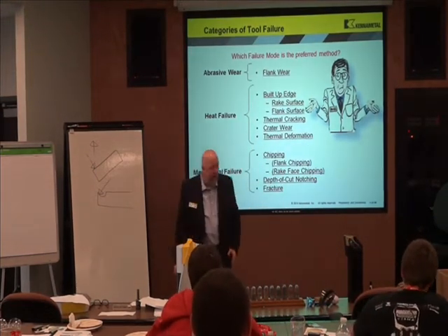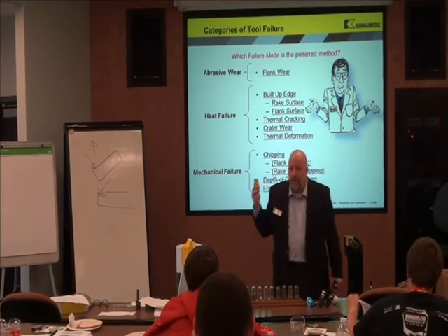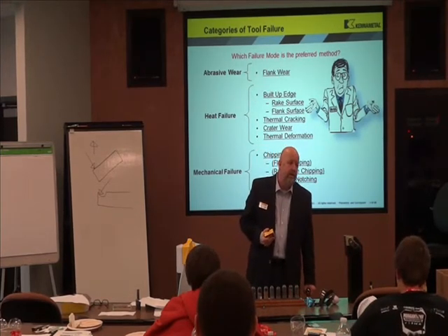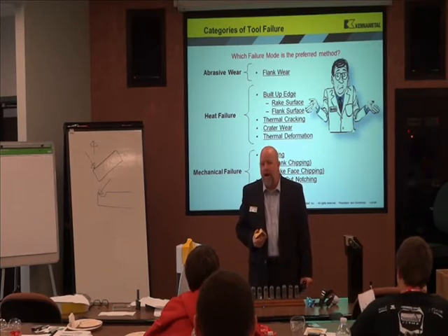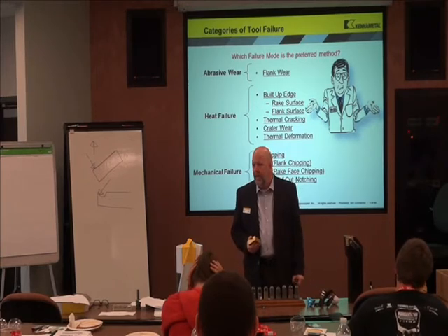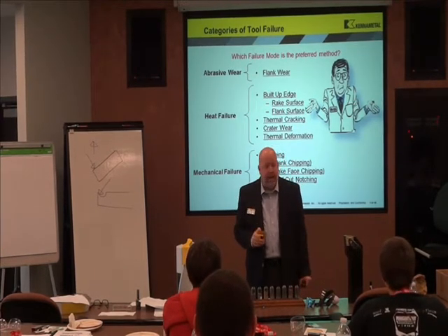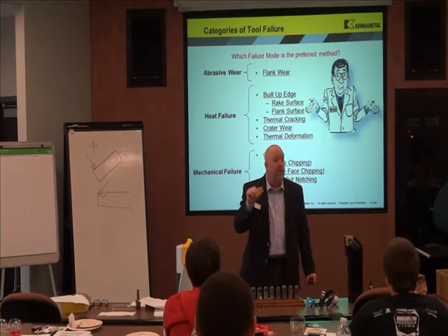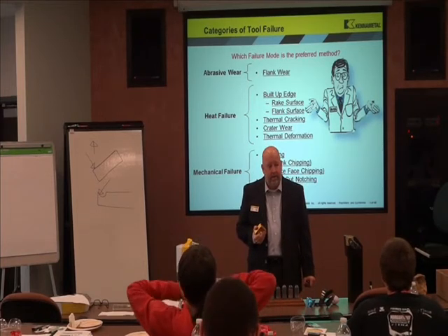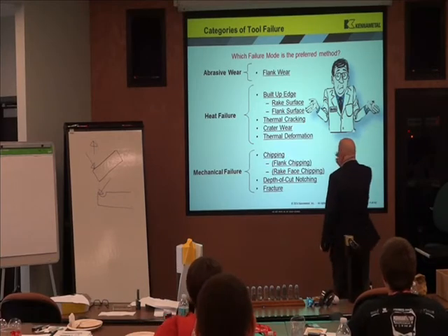When you look at tool failure, let's be honest with you. What I make, cutting tools, another name for them in the industry is perishable tooling. It is supposed to wear out. Perishable. It's like milk. Keep it around too long, it wears out. This stuff does too. You use it too long, it wears out. But here's the ticket. You want it to wear out on your terms, not on its terms. So what you really want to happen is abrasive wear.